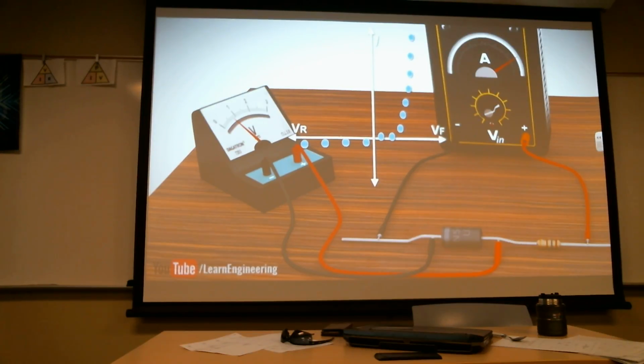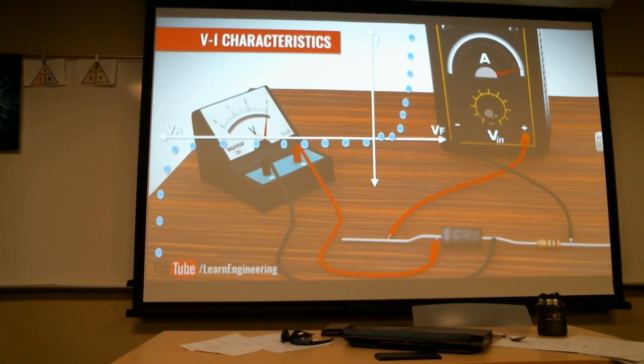However, you can note that the voltage across the diode does not go much higher than 0.7 volts, even with high input voltage. This is due to the diode offering very low resistance against the current flow in forward bias condition. At the reverse biased side, applying a very high voltage will damage normal diodes and result in a high current flow.